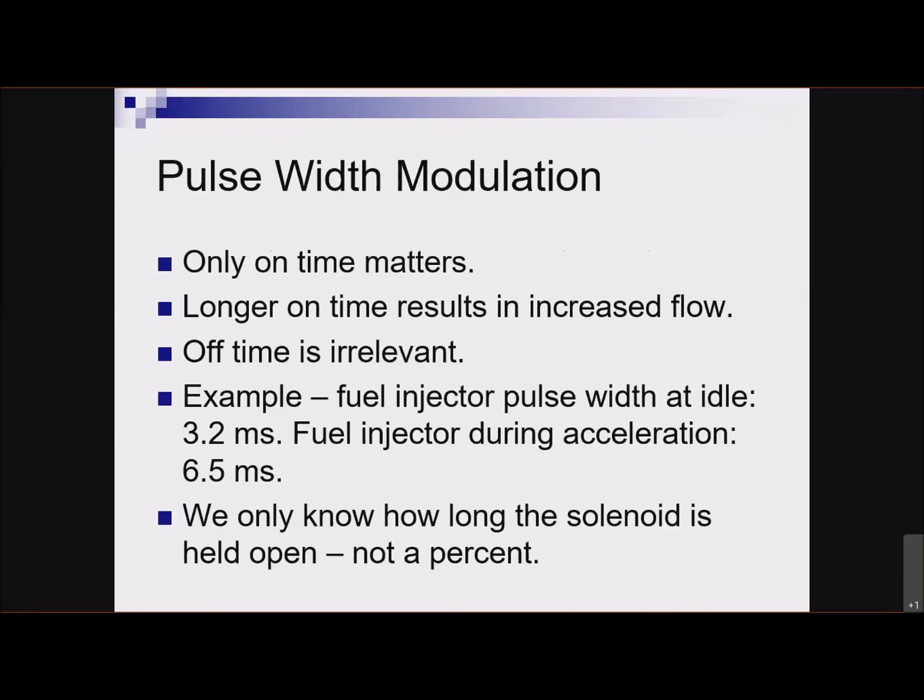All we care about is the on time. It's not a percentage. It's measured in milliseconds. So if you see something measured in milliseconds, then it's pulse width modulated.